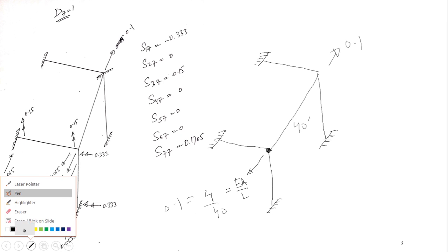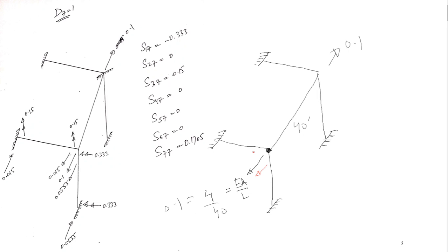Now there would be translation in the shoulders, and you know the magnitude when you give a translation to any point in the stiffness method is equal to 12EI by L cube. That would be equal to 12EI by L cube as well. All would be. Now the question is, what value of EI should be used? It could be x, y, or z.